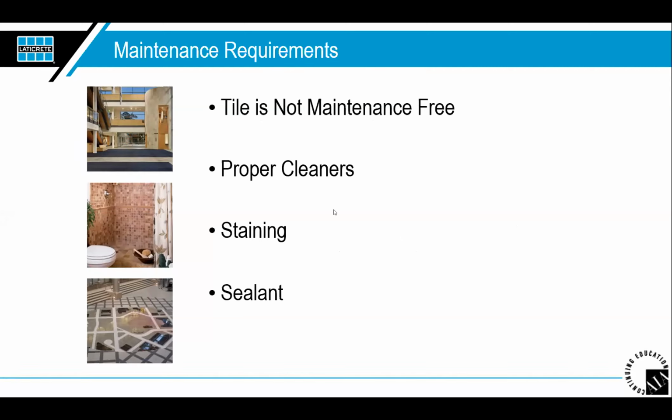Okay, well, I did have a house. It was a new construction. And when they built it, they had this expansion joint in the slab. And the tile kept cracking after they installed the tile. I had them come back, replace the broken tile, but it was reoccurring. But I think they didn't put down a membrane, either a rolled out membrane or a liquid membrane, over that expansion joint. Okay, gotcha. Sure, and yeah, they definitely would have wanted to.